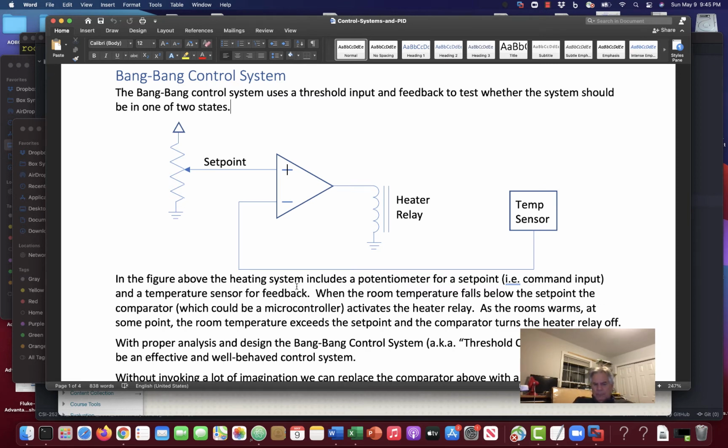You can build monostable or one-shot circuits, and you can build bistable or two-state circuits. But most importantly, with hysteresis, you get two thresholds with the 555, one at 2/3 of supply, one at 1/3 of supply.